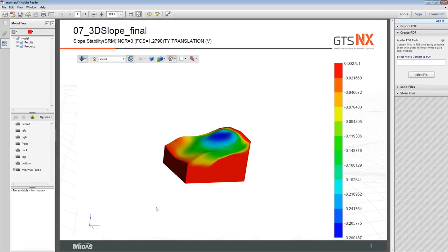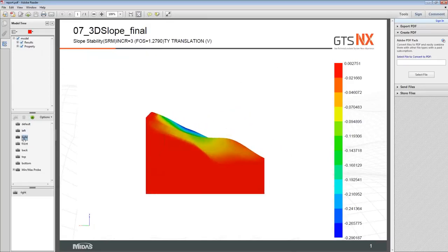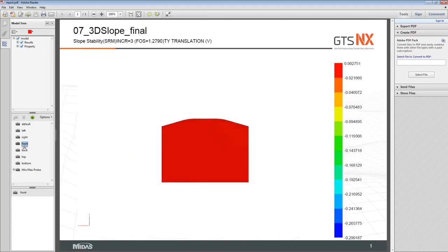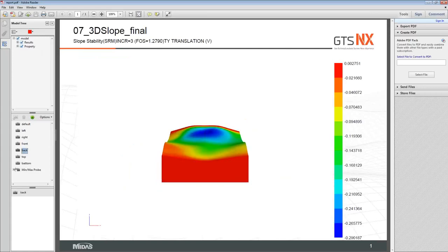Whenever we do the finite element analysis, we need to consider a particular view of that model, so working with the model to generate the report becomes very tedious. So what you can do is rotate the model within the PDF itself and just save it for your report generation, which will be directly in PDF format.